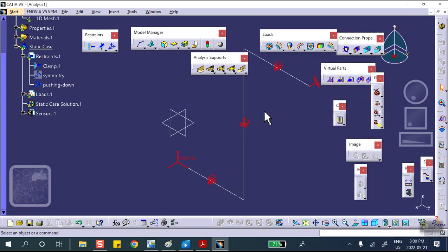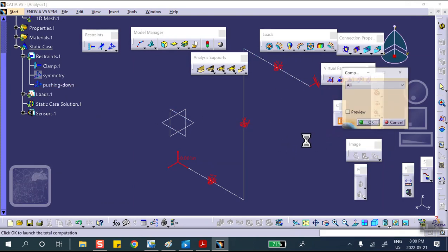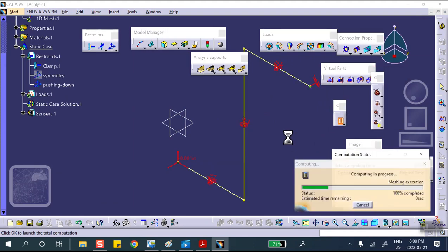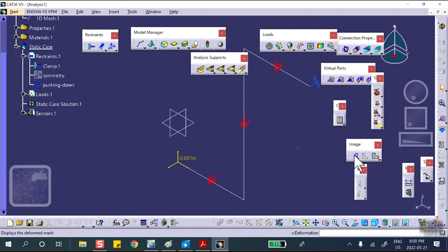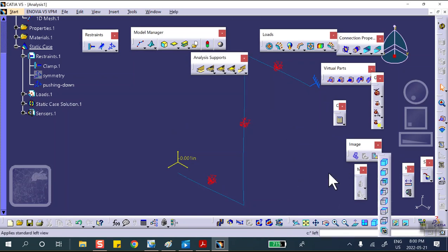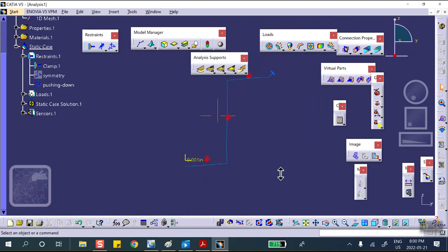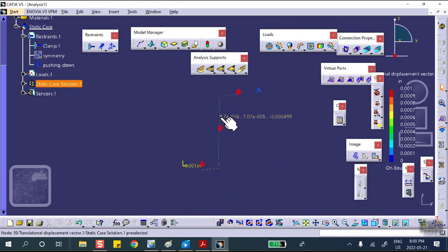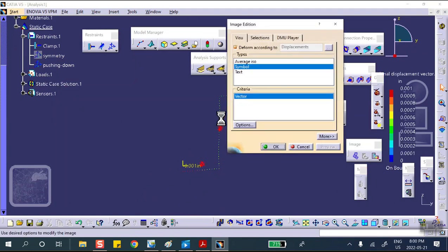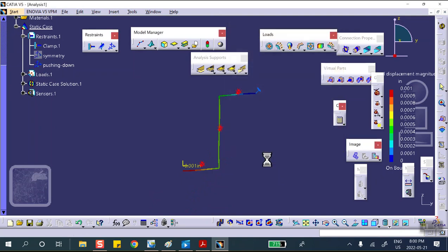good. We're going to run it. Yeah, so a deflection like that. If you look at the view from the front, there we are. If you want actual numbers, you click on displacement. And if you want color, a colorful contour plot, like that. Obviously, I pushed it down by 0.001. I don't expect anything to get here, anything else to get here.